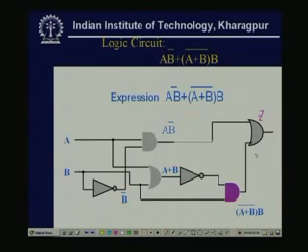So, in this way, what we have done is, if a Boolean expression is given, then we can draw a logic circuit, that means a number of logic gates with the interconnections, so that it realizes that expression. That means if I give the input values in terms of zeros and ones, the output value of the expression evaluated, the logic circuit should evaluate the same value for the same input set, and then we can tell that the Boolean expression is correctly converted to the logic circuit.